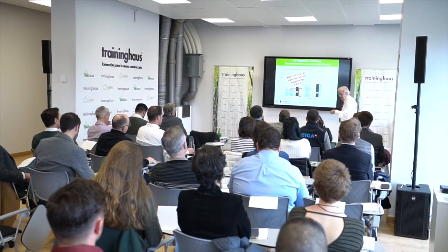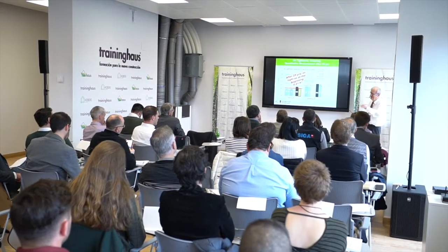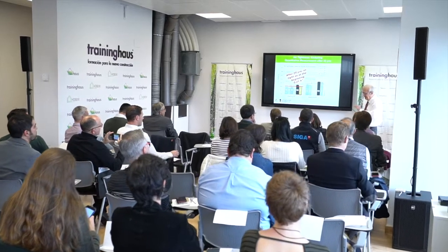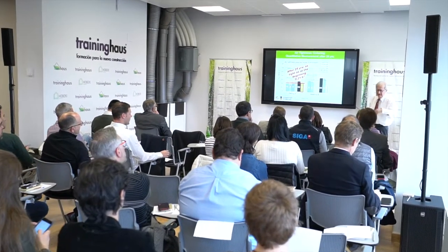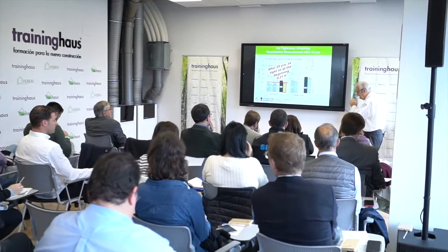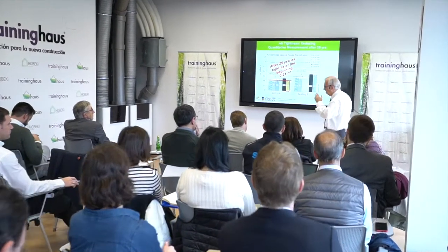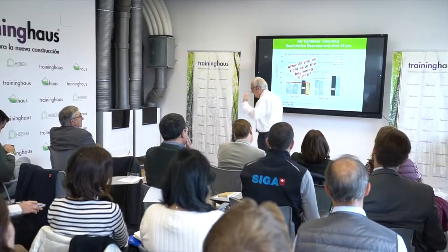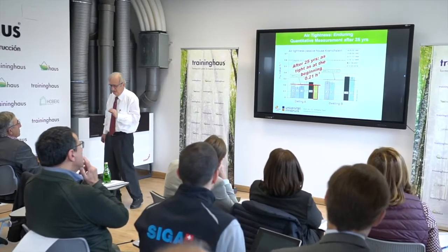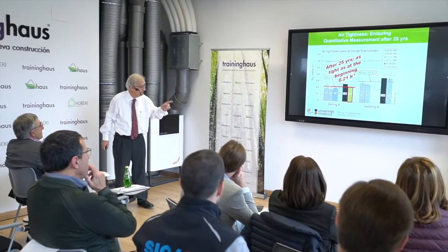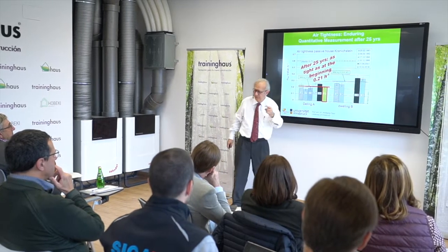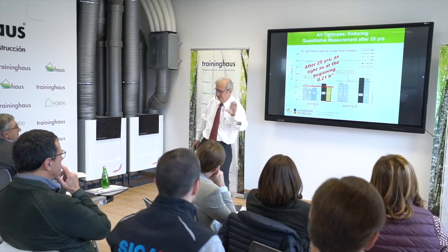An interesting thing with that very first building, because we didn't know about any of these things when we built these buildings. We only knew that it's important to make it airtight, and we were surprised ourselves. Our goal at that time was, maybe we can achieve at least a bit better than 1 air change per hour. We were surprised that at the very first measurement, we already achieved 0.24, because we were very cautious in all of these details.